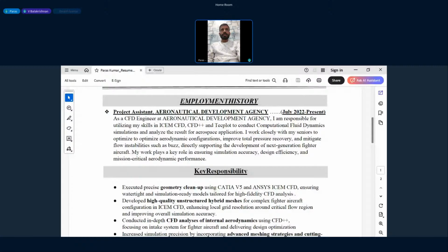What is the purpose of an inlet vane? Inlet guide vanes, sir, in my duct is not there. Maybe the compressor is having, but in the duct is not there. So what is the purpose of the inlet vane? Sir, inlet guide vanes are used to prevent the swirling and the non-uniformity. It will guide the flow linearly to the compressor.